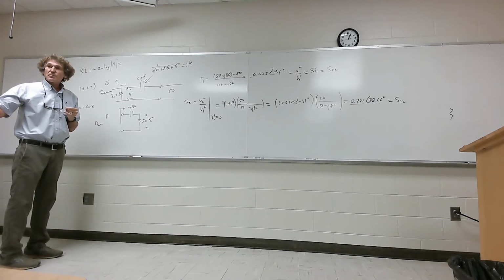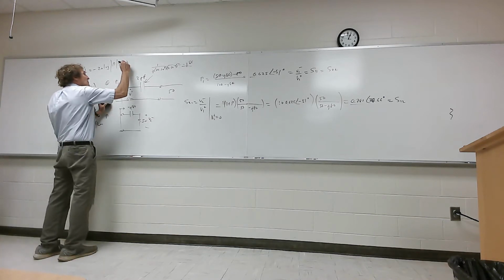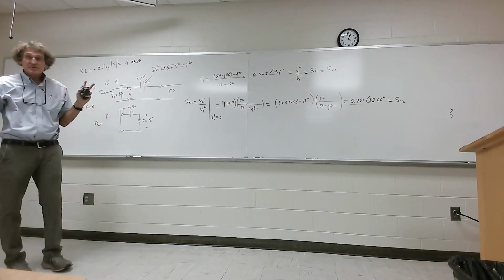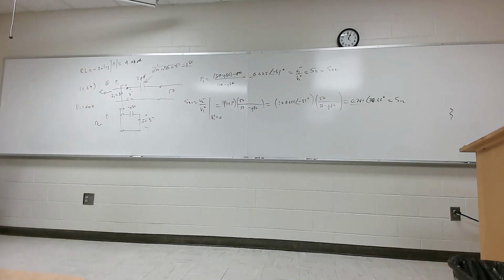Anybody confirm that 4.08? 4.08 dB. Y'all follow me. It's that simple, but you've got to take a magnitude. Don't take a real or imaginary part and take the log of that. I have people doing that all the time. It's the magnitude. That's the return loss.